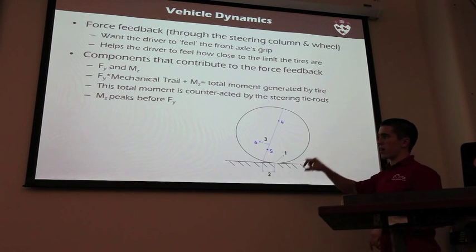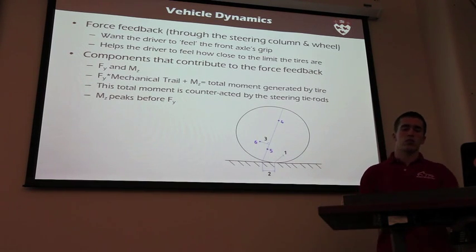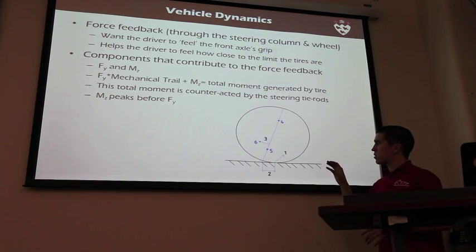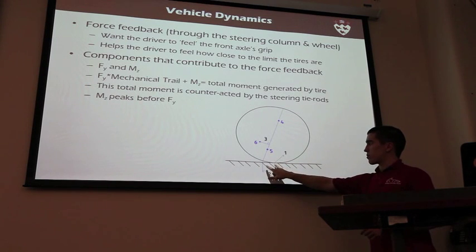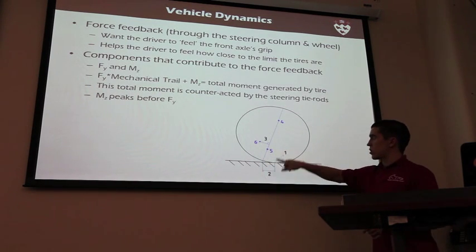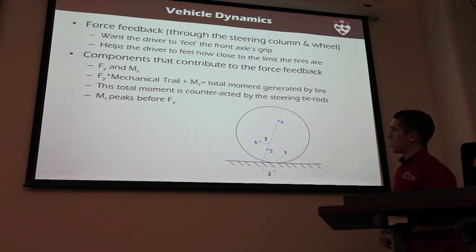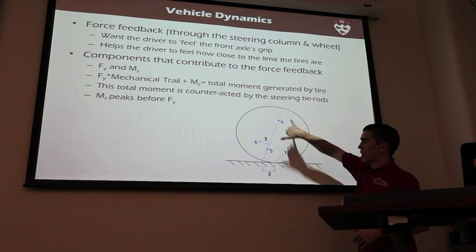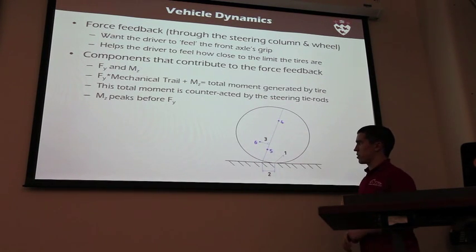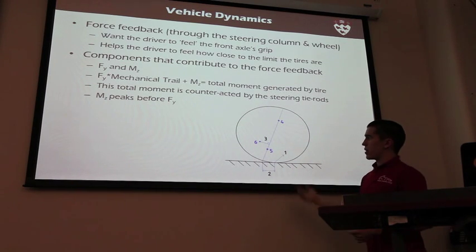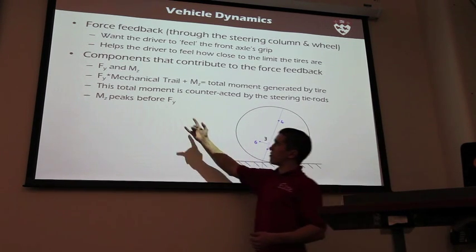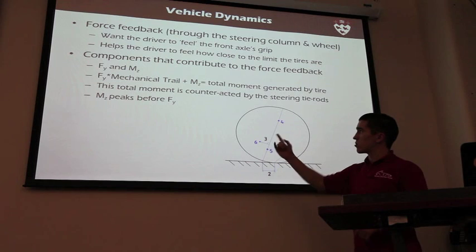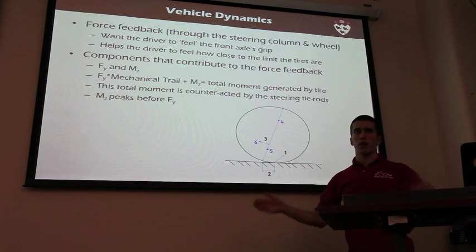So there's not only that, but there's also other suspension kinematics considerations. But if we only consider steering, what will affect the mechanical trail, which is the only factor affected by those 2 points, will be changing what we call the kingpin inclination, or the caster angle, and the offset basically, which will make that bigger or smaller. And varying the mechanical trail will basically vary the proportion of the contribution of Fy to the total moment generated by the tire.